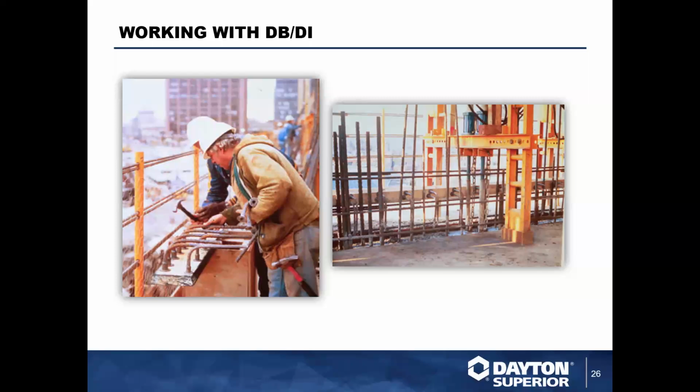You can do this with jump systems. Here's a project here in New York City that was done quite a few years ago, because this is when I first started in this business. This system was actually put in place and used on a jump system on a high-rise forming system. They're attaching it here to a recess void, basically to give it a little bit of a keyway, so that when the jump system moved up, they came back, slid the keyway off of it, and then poured their floor slab right at that elevation.